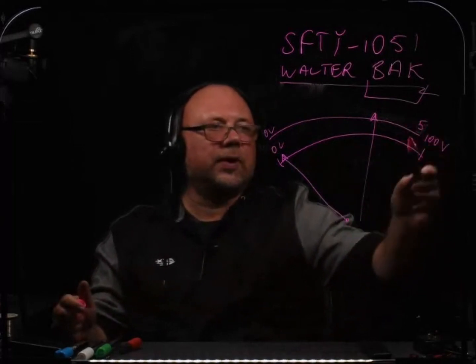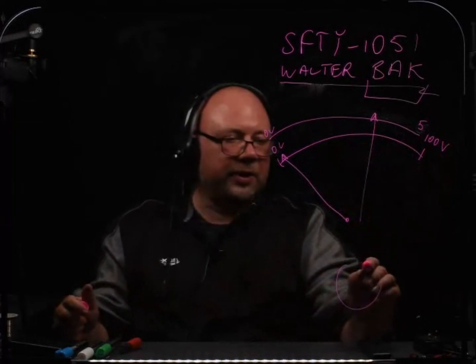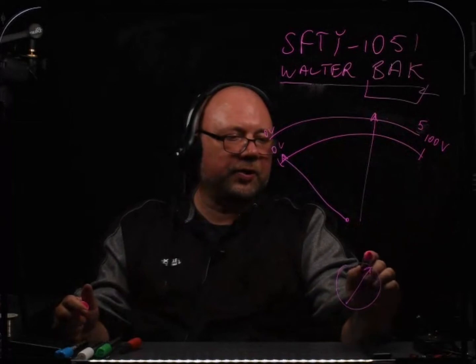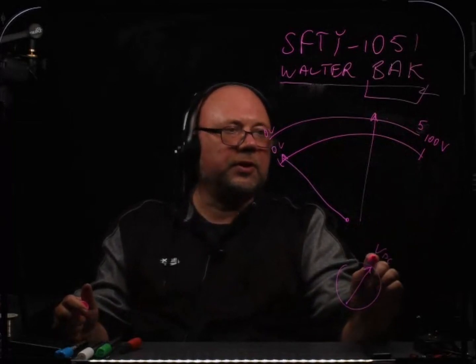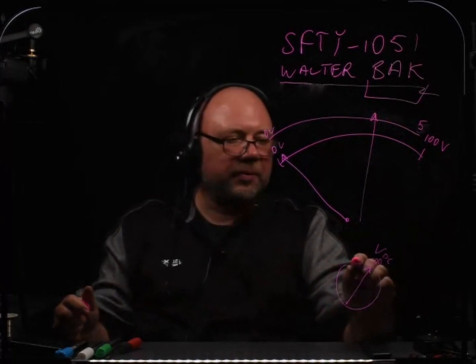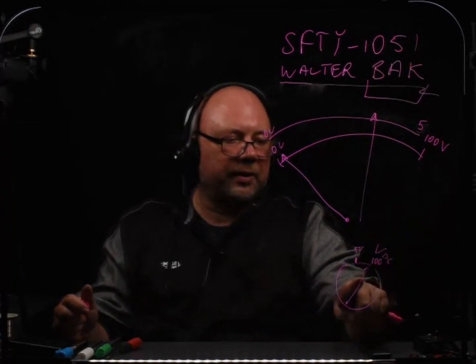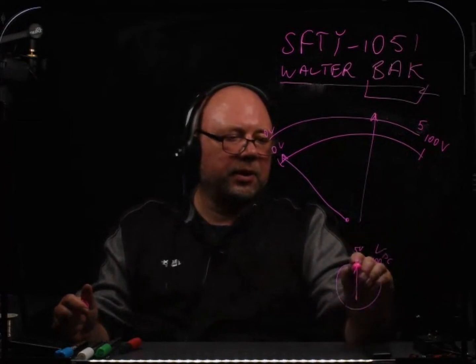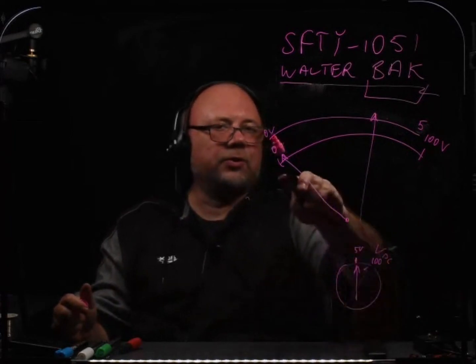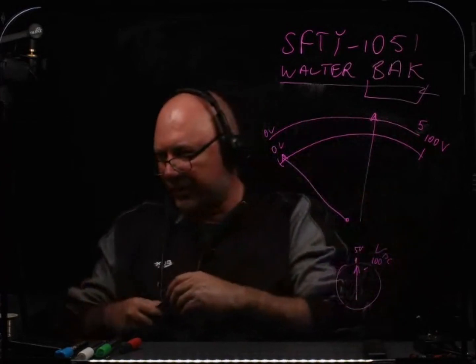So this is the range of 100 volts, and somewhere you're going to have a dial that you're going to select the voltage. Say volts DC. This is going to be up to 100 volts. And over here, maybe you're going to have another one that says up to 5 volts. So I would just move that dial right here. If I move the dial here, I'm going to use that scale right now, the top one. So that's as far as selecting ranges.